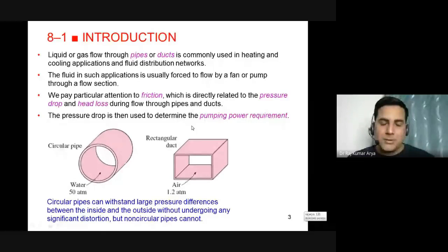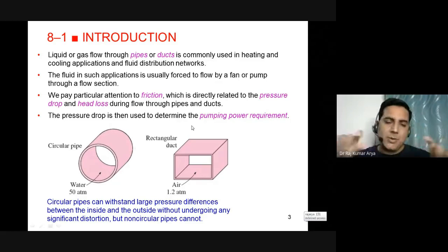So nothing will go in unless the outside pressure is not more than that, right? So same thing in the case of pipeline. In a pipeline, you will connect some reactors, some columns. So if the pipeline pressure is low, something would come out from the column to the backside. To avoid the backside flow, you should have a pressure more than that.